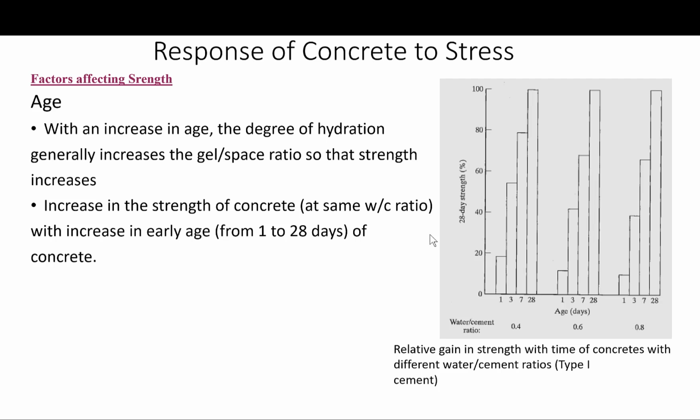So that's obvious. With increase in age, the degree of hydration generally increases, and the gel to space ratio increases, so the strength increases. That's very obvious.